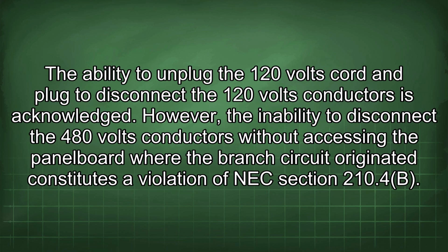The ability to unplug the 120 volts cord and plug to disconnect the 120 volts conductors is acknowledged. However, the inability to disconnect the 480 volts conductors without accessing the panel board where the branch circuit originated constitutes a violation of NEC Section 210.4(B).